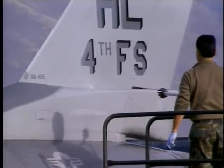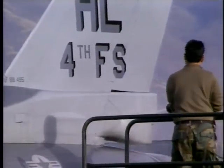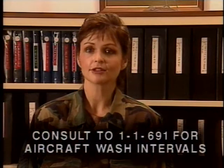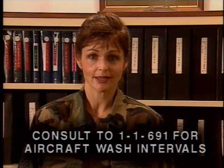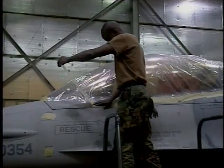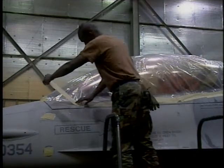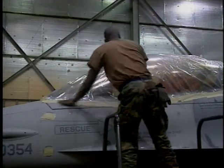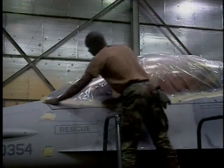Two of the most important preventative measures are quality aircraft washes and frequent wipe-downs. The cleaning schedule of an aircraft should be tailored to the environment in which it is operating. Before starting the aircraft wash, you must ensure all areas that shouldn't be exposed to cleaners and solvents are covered. Check the applicable aircraft tech data for these requirements.